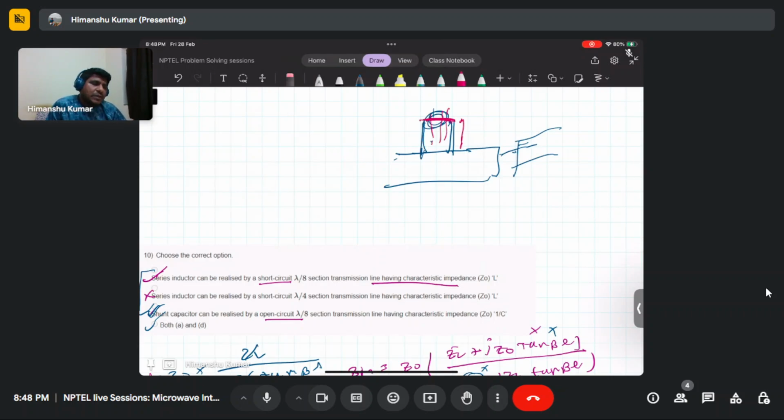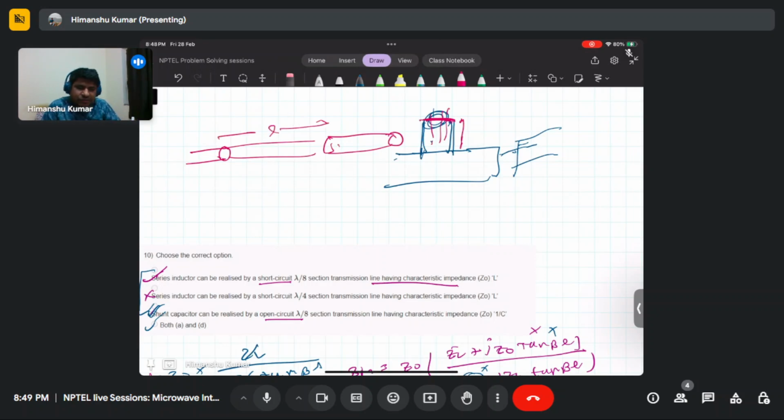Short circuited, and in series you can use open circuited. In series, open circuited is better. Let's say this is a coaxial cable and now you want to match to this antenna. If you use short circuited, then it's not possible. So if you want to connect this line to this, then basically some length L you use an open circuited line.